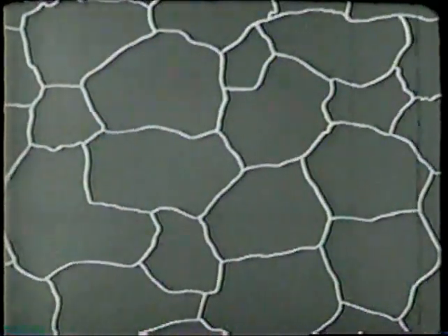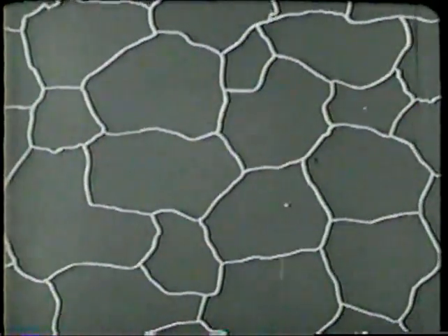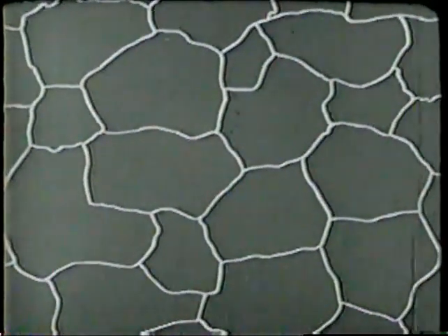When the temperature is raised to a point called the recrystallization temperature, nuclei of new grains are formed from the fragments and crushed particles of the original grains. As the metal is heated above the recrystallization temperature, but below the melting point, these stress-free crystal nuclei grow into new equiax grains by merging with the other nuclei and by accretion of material from the surrounding stressed metal. At elevated temperatures, the new grains may become quite large. The alloy is now in its annealed or soft condition.